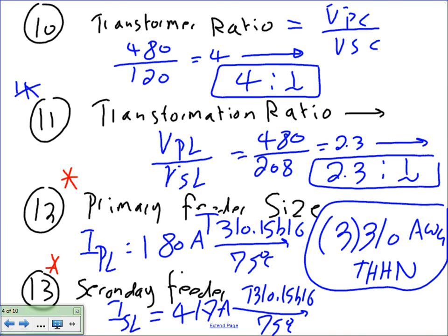And then if you go there, how many conductors do you need? Well, I need at least three. I have a neutral. Do I need to derate the neutral? You could derate the neutral at this time, but right now I don't want to derate the neutral. If you go there, the conductor is 600 kcmil. I need 3 conductors. I'm going to go full neutral this time. So how many conductors do I need? 4. What's the insulation? THHN.